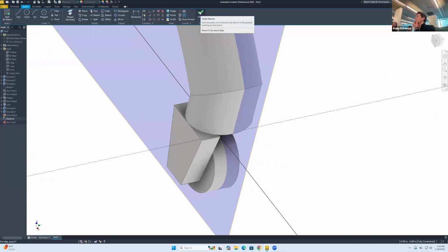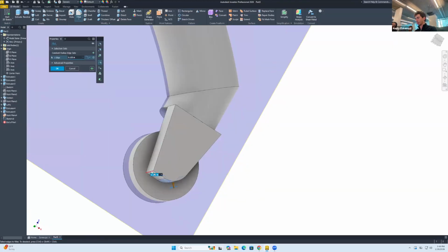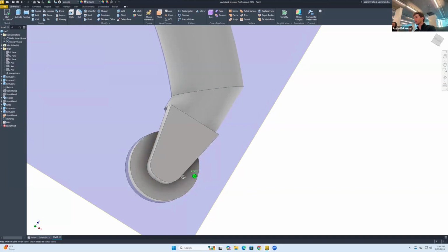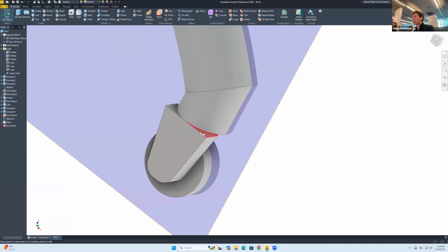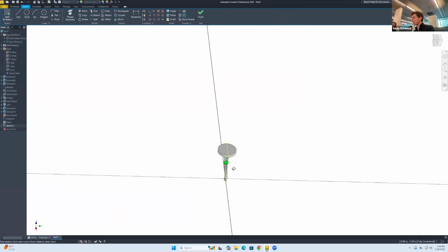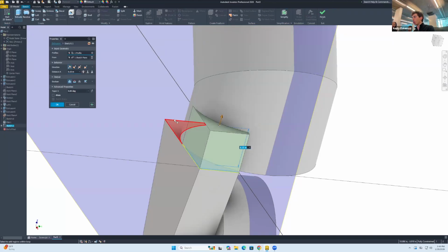I'm thinking strategically about the order of operations, right? So I'll do a fillet first on these two sides, 0.1. Okay, that way it looks like the bracket in there. Now sketch on this face. And we're going to project geometry that and that. Then 3D model, extrude. We're going to say through. Oh, that's good.